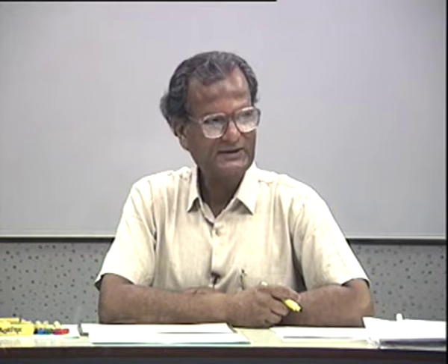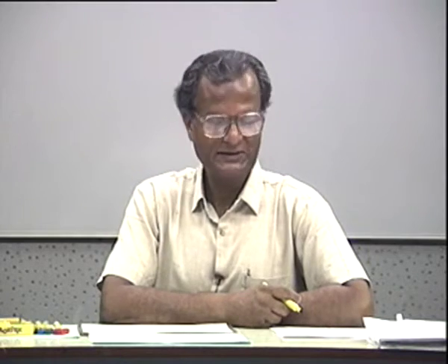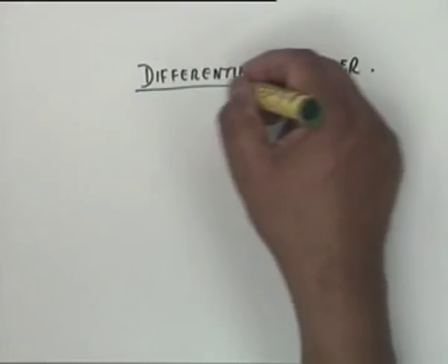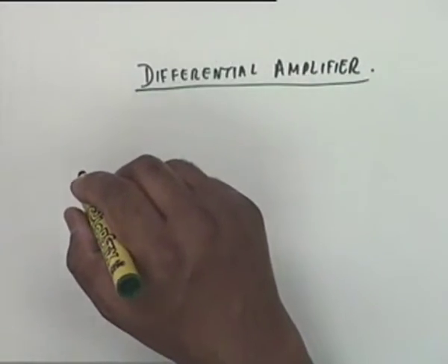One of the circuits, I don't remember in which minor I gave this circuit, had the modification that one of the transistors didn't have any load in the collector. That circuit I had used intentionally because it is a very popular wideband amplifier without affecting the CMRR or the gain.